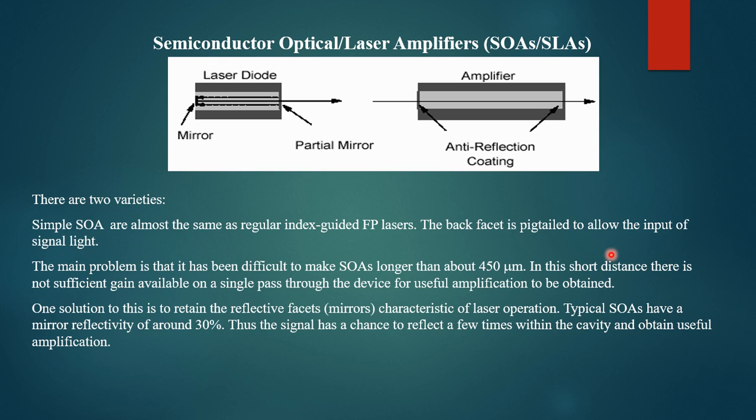This originates from the short, nanosecond or less, upper state lifetime, so that the gain reacts rapidly to changes of pump or signal power, and changes of gain also cause phase changes which can distort the signal. This nonlinearity presents the most severe problem for optical communication applications.